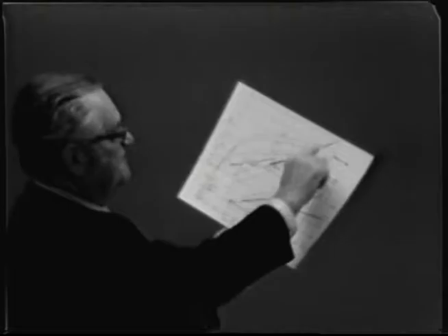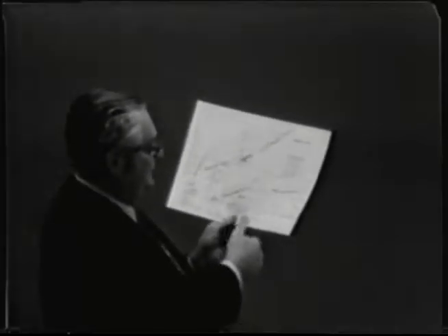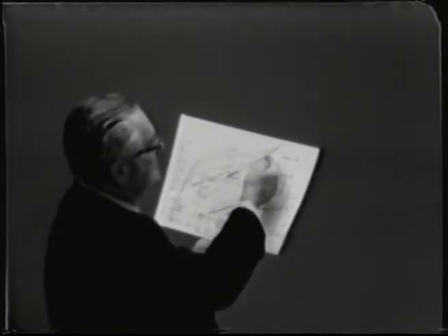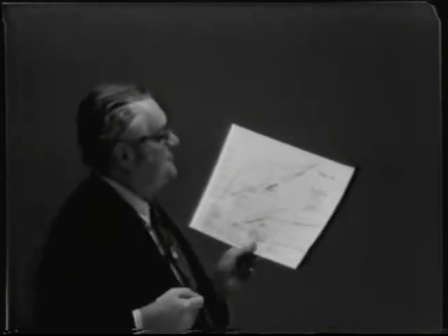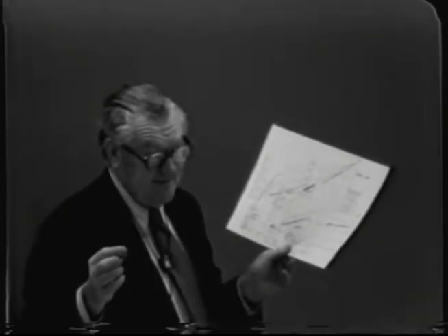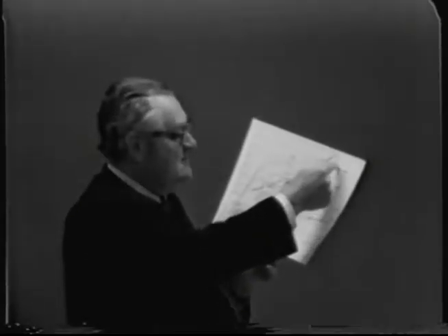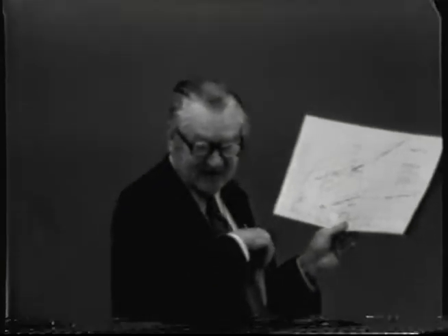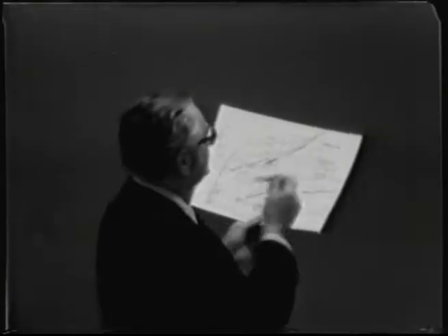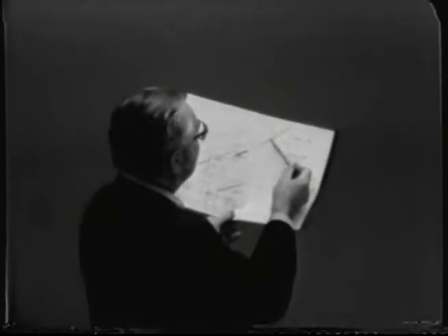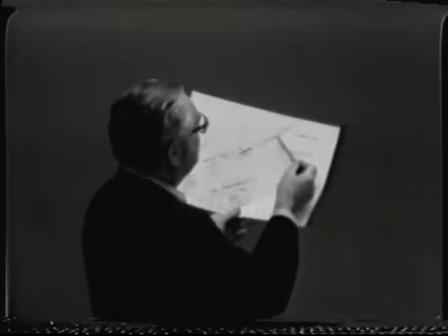So we've drawn the operating line now from the x sub D of 0.856. As near as we can draw it, a slope of 0.99 is essentially right on the diagonal, so you can't tell the difference between that and the diagonal. So for this little stretch, the operating line is for all practical purposes the same as the diagonal.